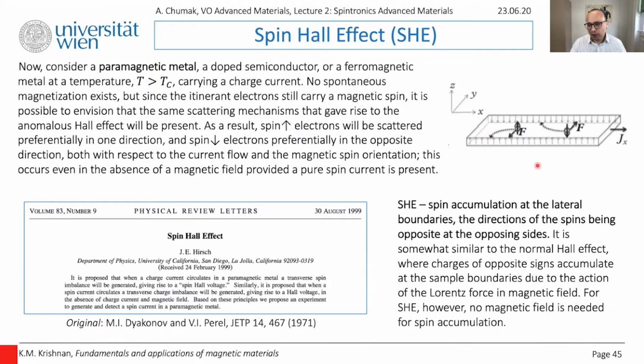Once I even played around and tried to check, it was only 10 nanometer platinum. There was a sample of 3 by 3 millimeters. I placed it on a piece of wood and tried to see at which current I should apply in order to burn it out. And I think at around 1 ampere current, the wood was already black under the sample, so it was already a very high temperature. My substrate broke down, but platinum still was fine. Therefore, platinum is very stable, and you shouldn't worry if you need to work with high current densities. It's a very nice one.